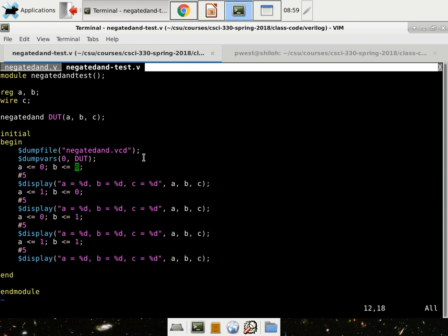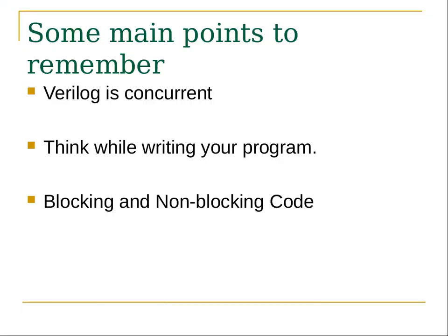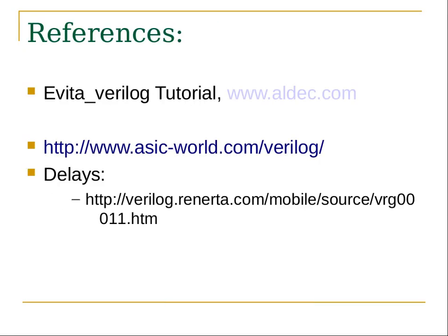Also, please, always do your assignments this way. If you ever do that, it becomes a blocking assignment, which means it waits 1 tick before it continues, and your code is going to become really, really confusing. Don't do it that way. Okay? Leave it like this for now. Your life will be happier. Trust me. Not you, but your life. All right, I think that's it.